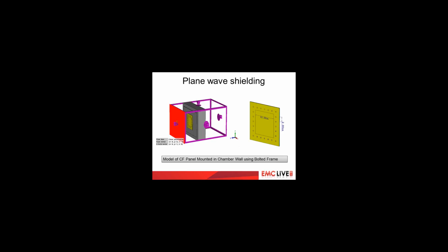Just a note about the test setup here. The aperture size in the screen room is about 10 inches, and the cover plate is bolted to the aperture on a 2-inch pitch. These dimensions become important at higher frequencies, as we shall see in the following slides.